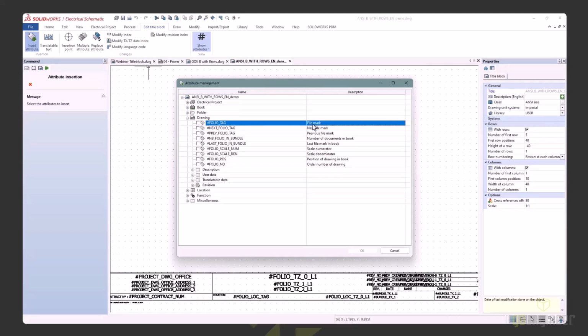because that way I can control what is being shown. Is it having a leading 0? Is it not? And I can define this in the project template, which is why I like using the folio mark rather than the order number. The order number is referring to what order you had created the documents. No matter what the number is, the order is which one is created first.